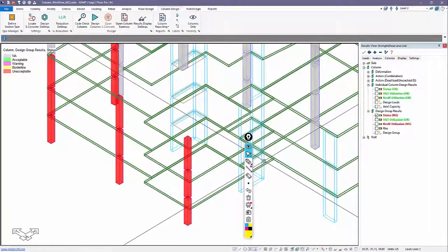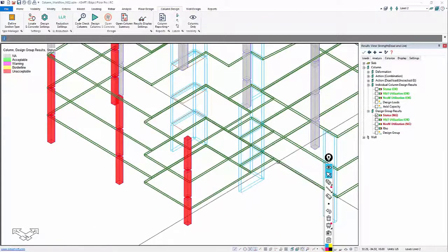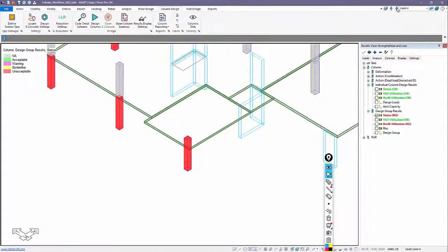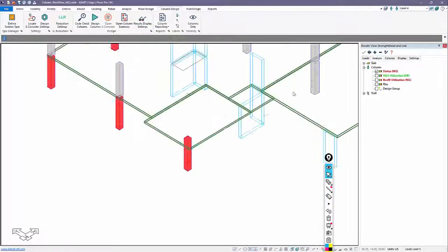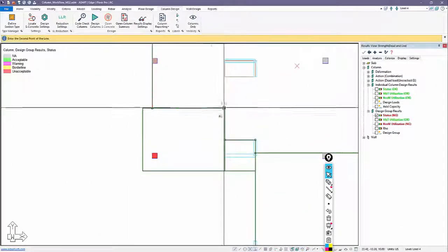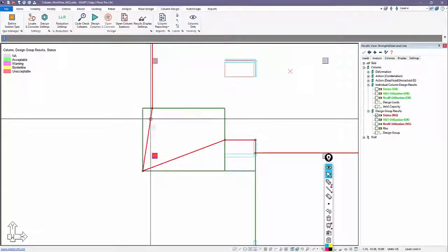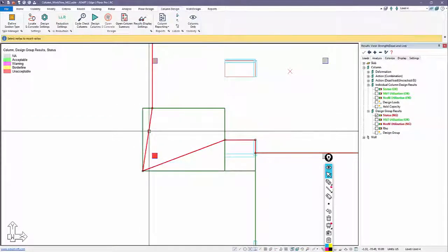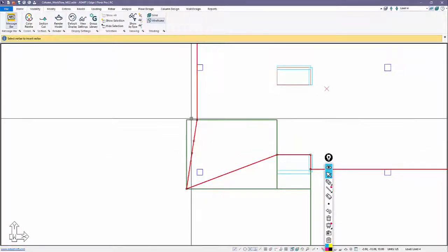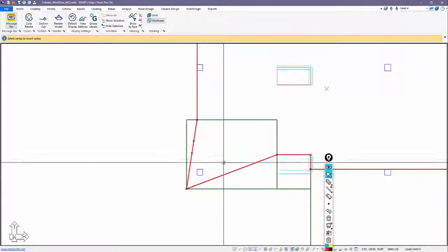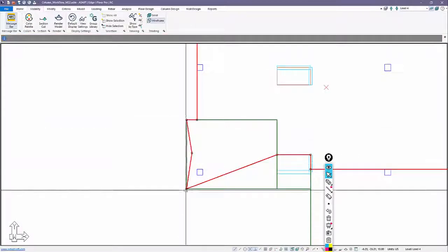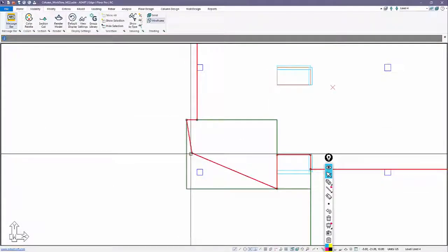So the way that we work around this in this case is we have to nest the slabs, and we're going to go ahead and do that. We'll go up to this level here, and rather than modeling this as joined, we'll nest this, and I'll just add a couple of points. I'm going to add point 1 and just 2 points is all we need. So we'll come back and just reassign the location of these points. This one I'll slide over, and this one I'll slide here.